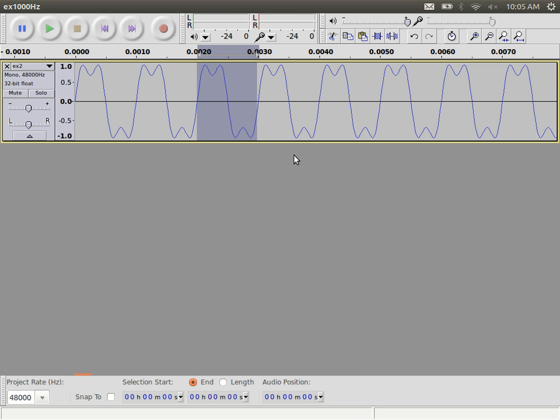Okay, so one point to notice is that the data rate on signal A is 2,000 bits per second, the bandwidth is 2,000 hertz. And in B it's 4,000, 4,000. Are they always the same? No. Just a coincidence in this case. So the data rate is not always the same as the bandwidth. It is in these two, but we'll see another example where it's not. Okay. Any other questions?